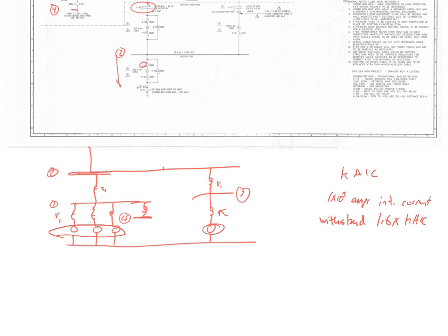And all distribution circuits, they don't make distribution equipment that has greater than a 10,000 amps interrupting rating. So if you have more than 10,000 amps of available fault current at your distribution center, you're putting some reactors in series with those, because you've got to knock the fault current down to what those can break. So all those fuse disconnects, you can see with a hot stick, we have a fuse that has to pop in. The fuse may or may not be able to handle the 10,000 amps. Usually fuses are fine. It's all the system itself. It has to swing up. It has to have current going through it. And if you have more than 10,000 amps, you literally could damage the fuse cutouts, reclosers. All those could be damaged.